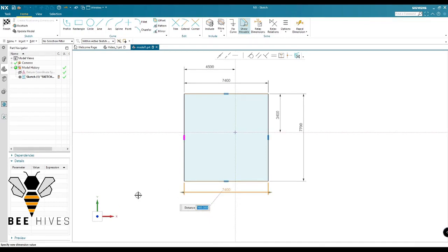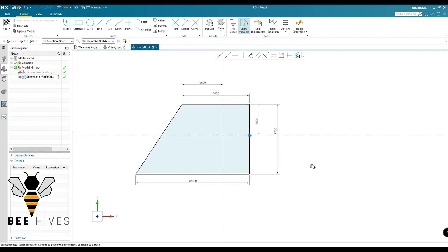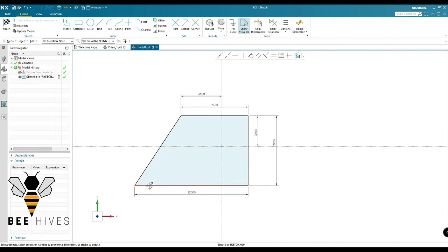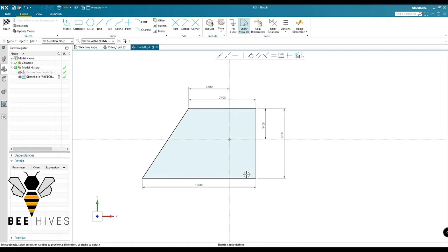You can change it. But what happens here is, if you observe this magenta colored constraint, it will get relaxed. There's a new feature called relaxation of constraints and dimensions. This relaxation is a new feature that will allow you to convert your basic geometries into profile sketches easily. It's a really nice thing for those who are used to drawing profile sketches, and it controls the dimensions very easily.